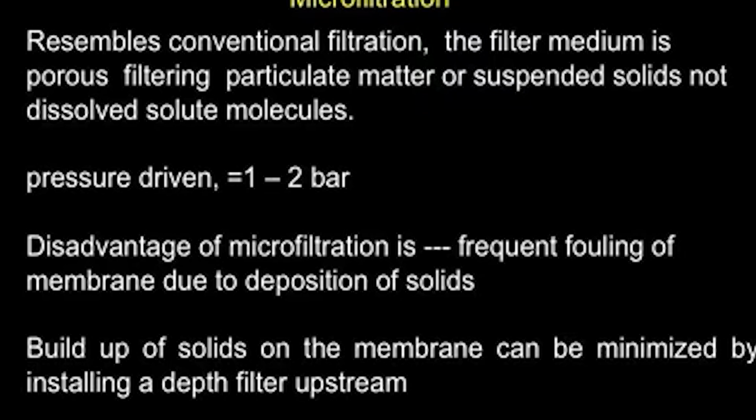Another disadvantage of microfiltration, because the pressures are not very high, you are going to get a concentrated slurry. You will not get dry solids after filtration. Ideally you would like to have a dry cake after filtration, because the storage or disposal becomes easy, whereas if it is a slurry it may contain about 10, 15, 20% water. So then it is not a very nice idea to store it. Where will you store it because of 20% water? So membranes will lead you into a slurry system, and you can't apply very high pressures because the membrane will mechanically get damaged. So that is the disadvantage of that.